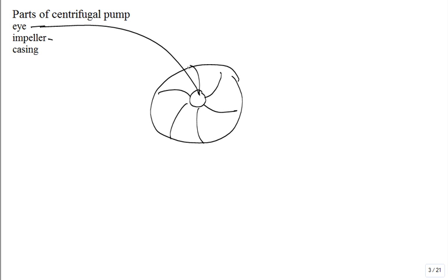It's just going to throw it out, and the radial pumps work. But if you have to know that it's going to be rotating this way, you're making sure it rotates that way from the motor, then the blades typically cut into the eye to bring it into this impeller region, and they throw it out, and it slides along, so it has some relative speed along the tips, and then it also has that tangential speed there, and then you have a vector diagram to get the composite speed of the water coming off of the tips of the impeller.